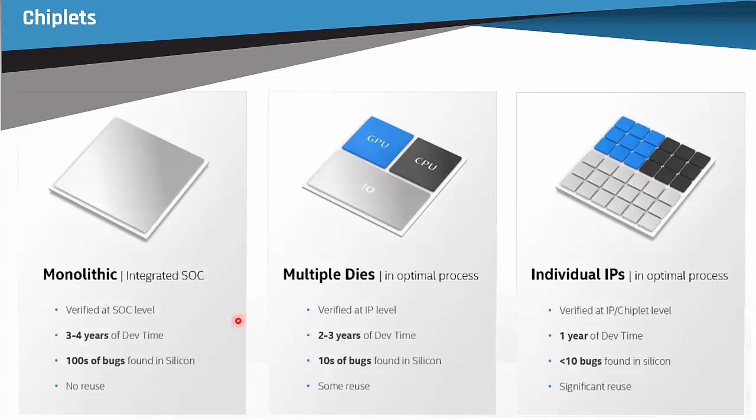And we put the chips that are much smaller on top of it and have them connect to each other through the substrate. So instead of putting, like Intel now sells you an integrated GPU, so you have your CPU and your GPU on the same chip, and we want it to be 400 millimeters or something. Instead of that, we put the CPU on one chip. Now it can be smaller and cheaper, or the same size and much more powerful. Next to the GPU and the I/O, which takes up a lot because it has to be analog and use higher voltages and so forth, we can even make it with an older process. And they're all connected through below here, underneath.